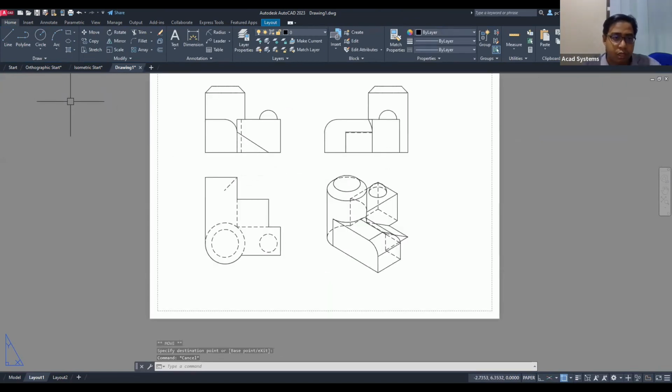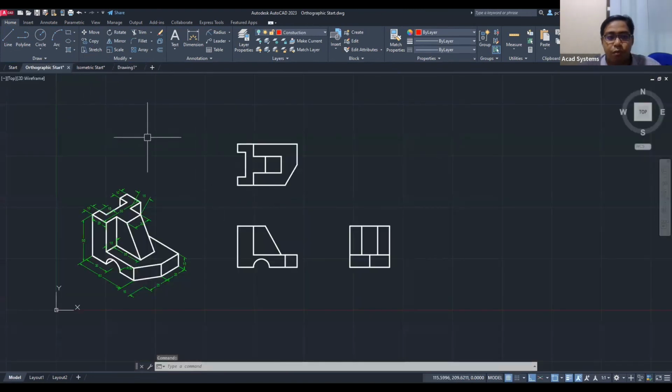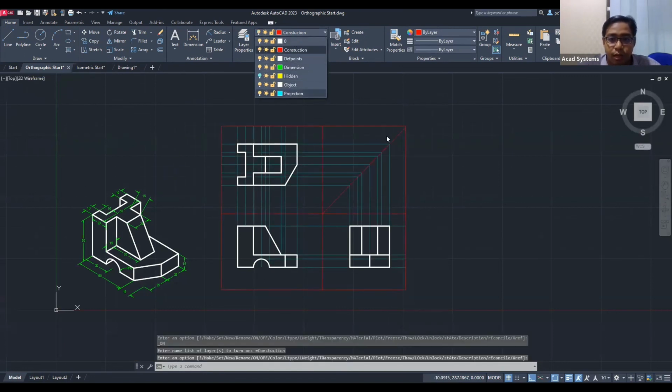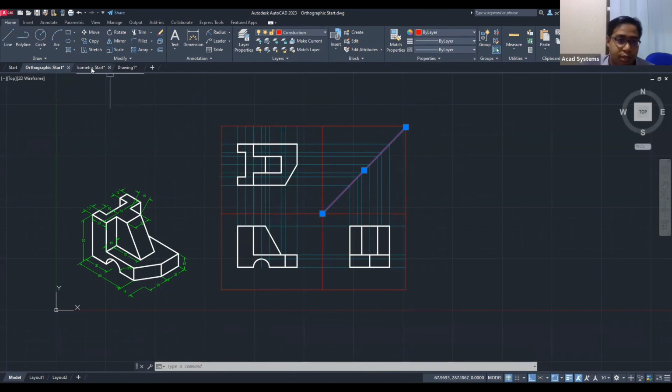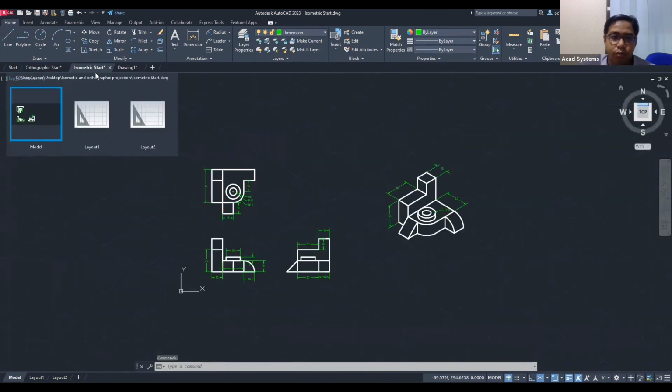But if you have the 2D object, you can use this method I have shown you before, isometric orthographic projection, where you needed to create a projection line and also these 90-degree lines over here, and we can create these other two types of view, which are aligned with each other, and also this isometric view.